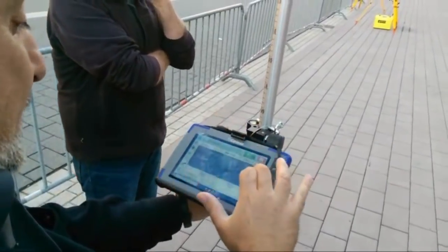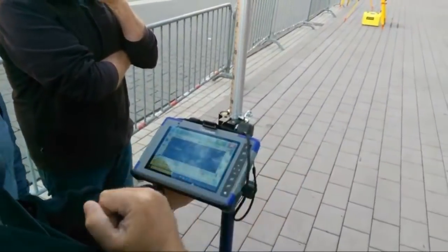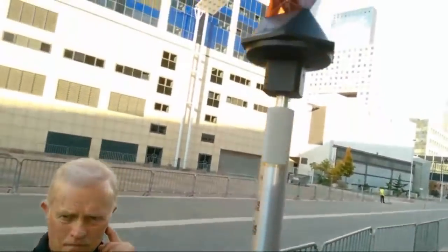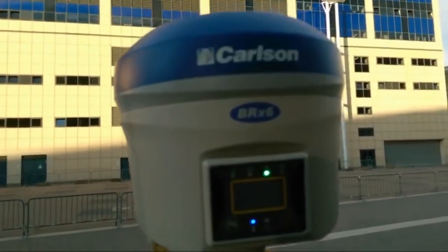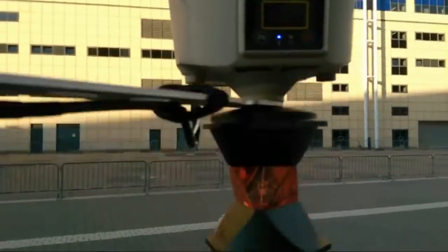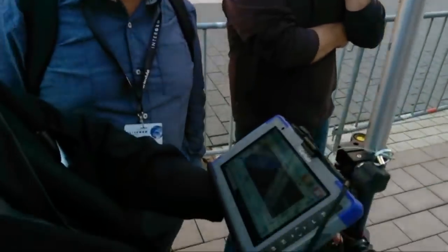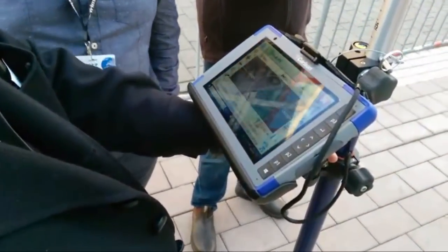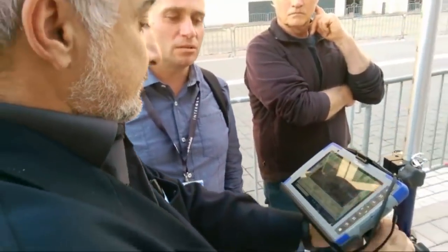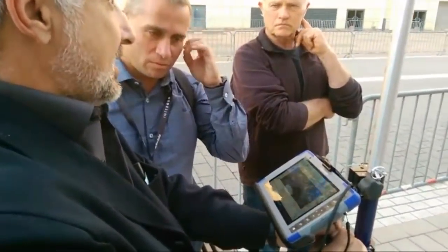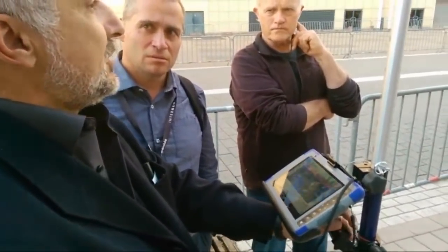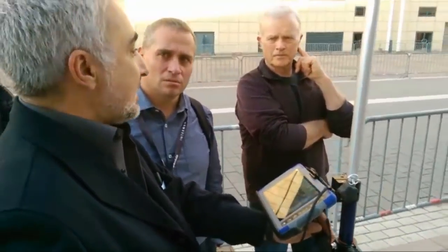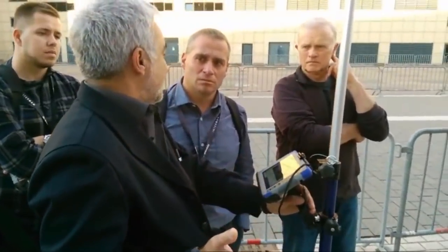If I say GPS and store, that means I want to store the GPS point for any reason. So I'm storing the GPS point, but in the raw file, I'm also storing what I got with the total station, because the total station also measures and is measuring the differences and storing the differences. That means the coordinates are stored from the GPS, but the raw data is from both. We don't write the final coordinates of the second instrument, but the differences, which are on the side. And if the difference is too high, then we warn them, right?